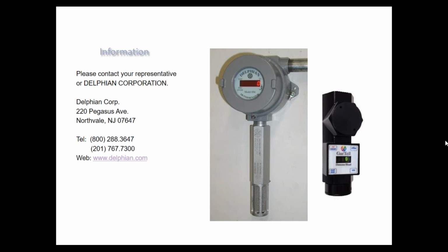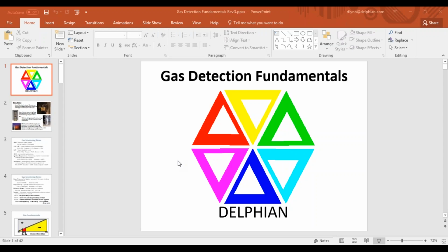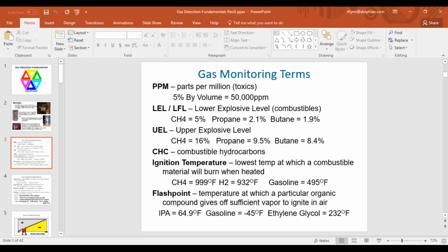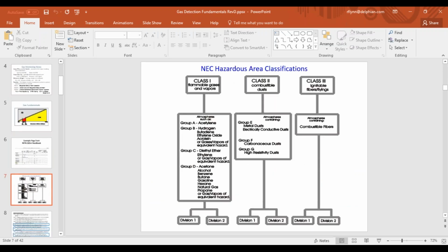Now, if you have a 5% LEL cloud over the entire 300 feet of detection, it's going to turn around and say you have a 90% LEL per meter leak. So it has no way of knowing how far across that entire 300 feet the leak is. So open path was really designed for go, no go. It's a great thing for maybe a platform or a company that doesn't expect to see gas, and if it does, wants to react to it, doesn't really care how